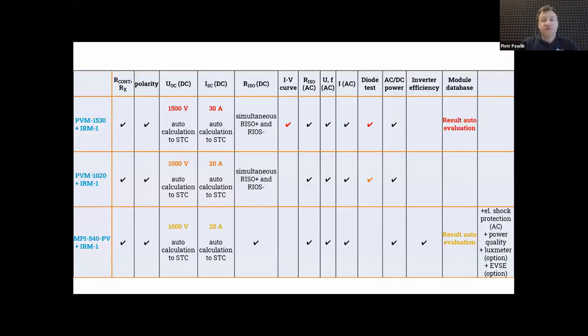And now further on the meters for electrical values. We need to make sure that the meter that we select can measure all the parameters as defined by the standard. There could be different meters for smaller installations. We need to check what is the maximum operating voltage and current, or for some bigger installations, like for the power utilities that provide solar power plants, they will work with higher voltages and currents.